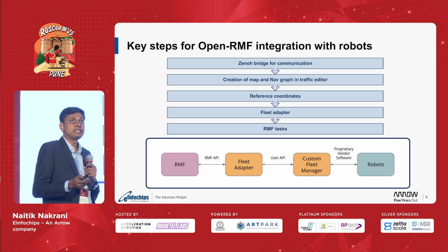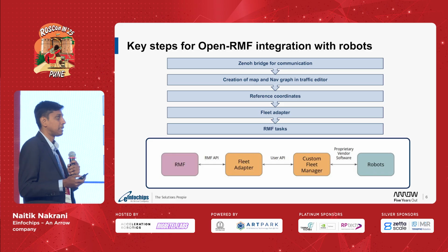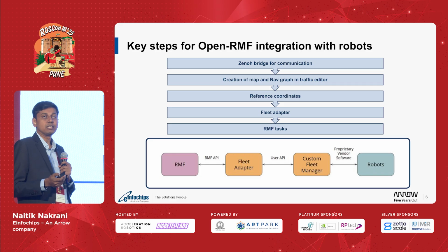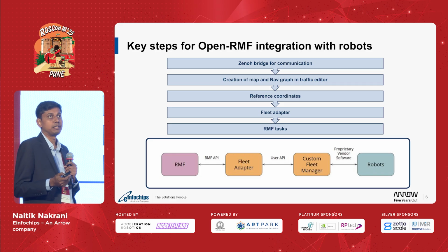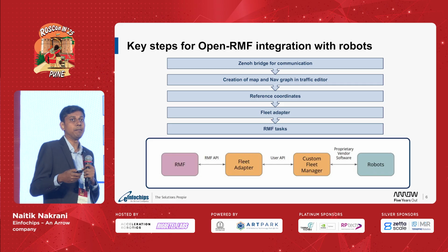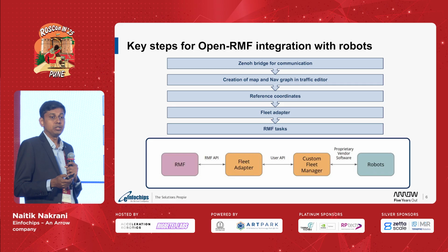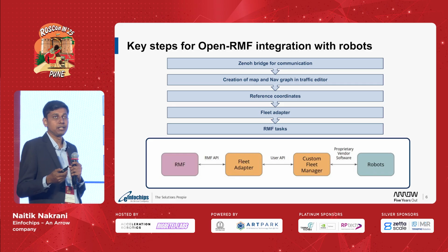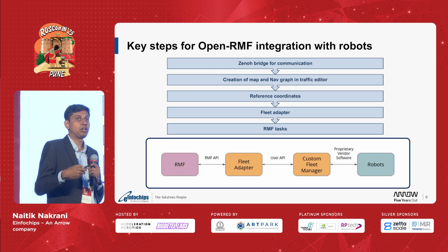So this slide shows you the key steps that you need to follow in order to implement an OpenRMF based implementation. First is a Zenoh bridge, which is a must for your communication. It enables communication between your physical robots and your OpenRMF core. Then you might need the creation of a map which OpenRMF understands, and you need to create navigational routes, or